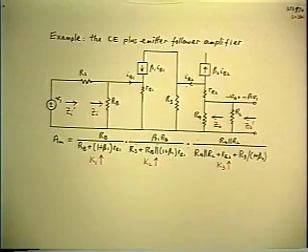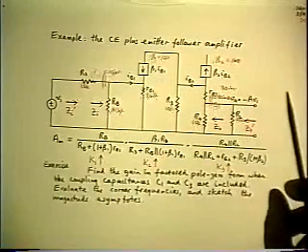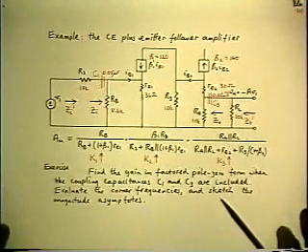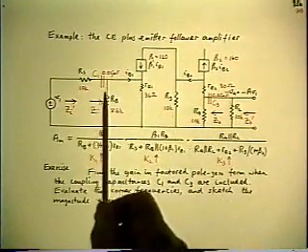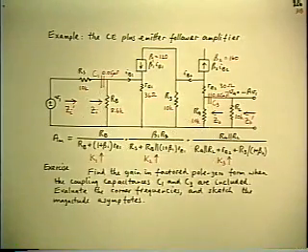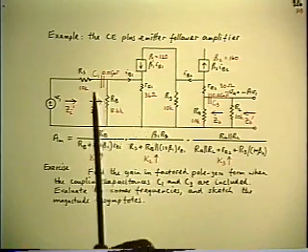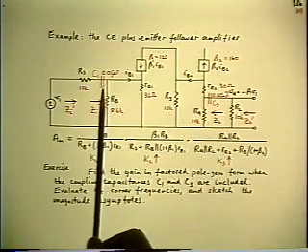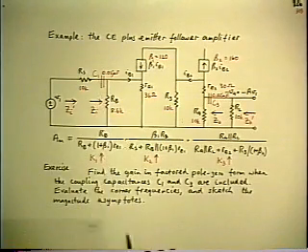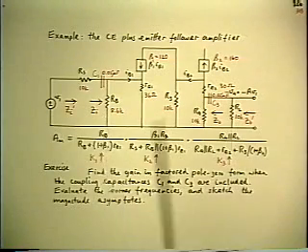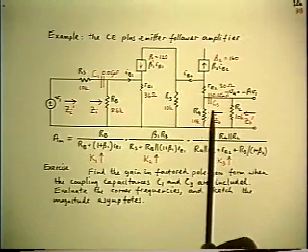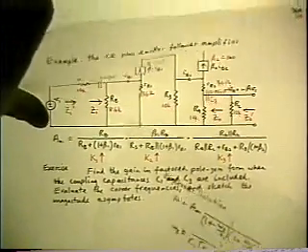So what we did finally was insert those capacitors and ignore the C2, again assuming that's a complete short circuit. And we discussed how to modify the gain expression to account for the C1 and the C3, which we did by using the extra element theorem in succession. First we put in the C1 and found that it had an inverted pole at omega 3 and no zero that goes with it. Then we did the same thing to put the C3 in. That also has an inverted pole and no zero with it. And the result was this.